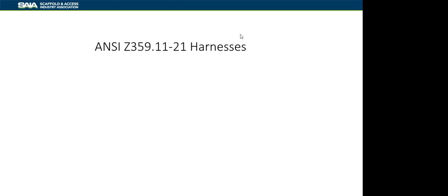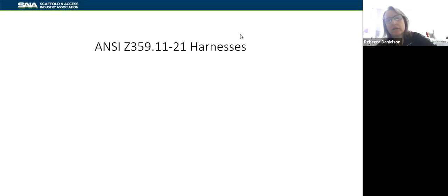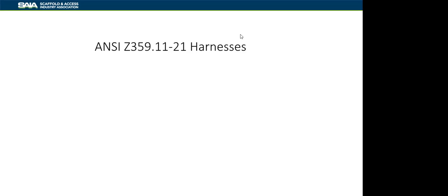So is that maximum 5 foot or 6 foot below your D ring in a class 2 situation? Well, you're only 6 foot of free fall or 12. So if you're at your feet, it'll be 12. So if you're hooking off to an anchor point, your maximum would be 6 feet, because then you got additional 6 foot for the personnel, correct?